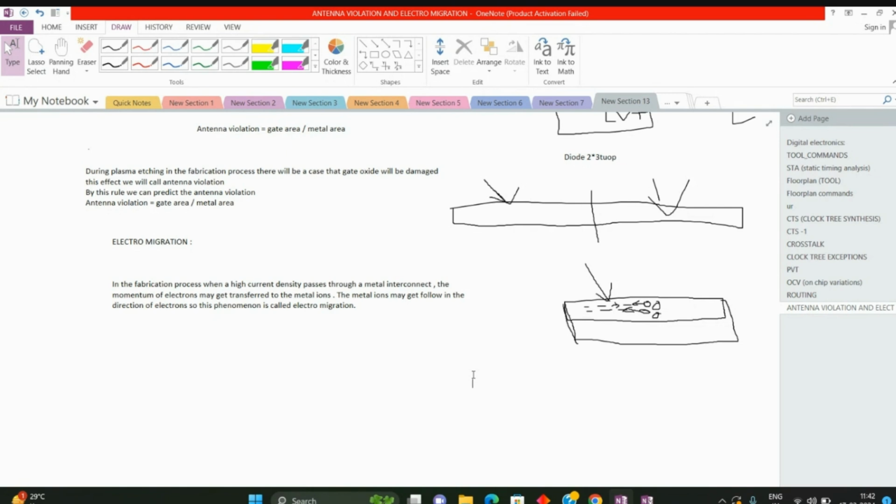So that's why after the routing is completed we go to the ECO stage. We don't go to the ECO stage in every netlist, remember that. For every project, netlists will be released, and it depends on your project. In Qualcomm we have only 3 netlist releases. After the 3 netlists, your project is closed; you need to do ECO and submit your design. But in AMD, 7 netlist releases. ECO phase means your chip is taping out. It has already gone to the fabrication stage, already gone to China or Taiwan. The whole project has already gone there.